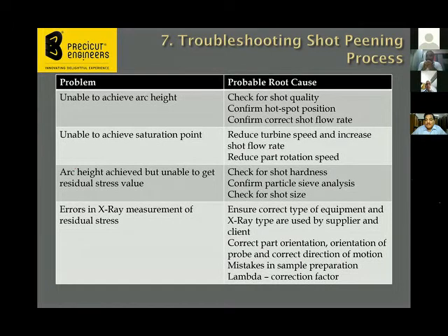Secondly, what you have to look at is the preparation of the part. For X-ray analysis, the part needs to be cut by, say, the wire cut method. You need to electropolish the parts and ensure that no additional stresses are developed or stresses are relieved during this cutting operation.